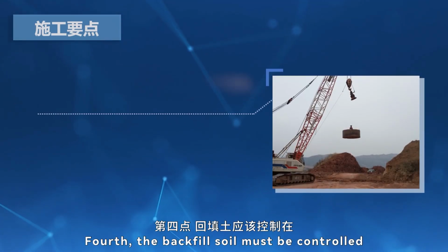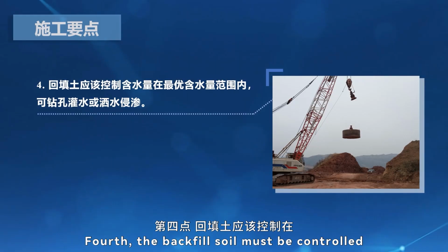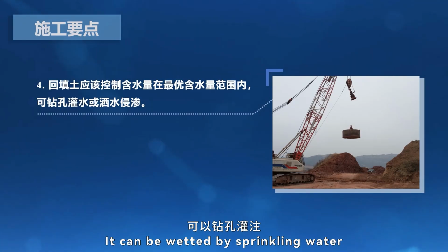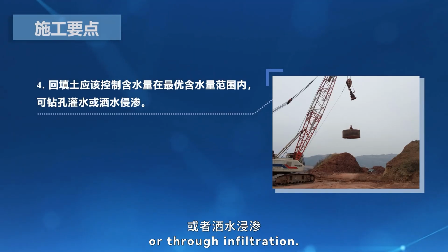Fourth, the backfill soil must be controlled within its optimal moisture content. It can be wetted by sprinkling water or through infiltration.